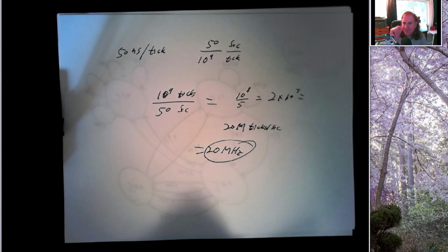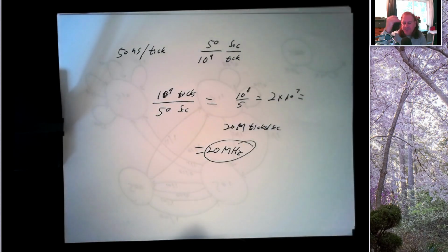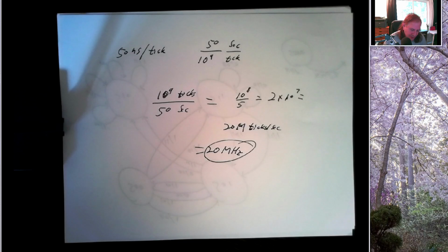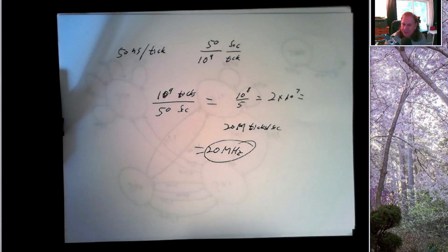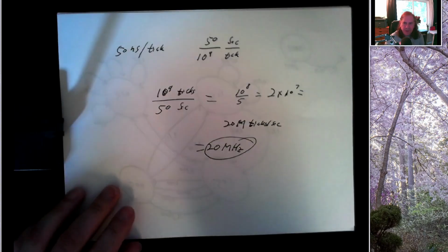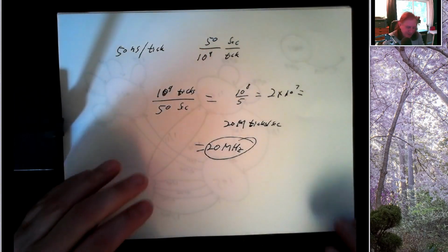And it's just a matter of using very, very small devices with very low voltages, so you don't have to swing a voltage all the way from 0 volts to 5 volts. We swing it maybe from 0 volts to, you know, 0.5 volts, and maybe that registers as a logic 1. And very low power, right? Not enough power to drive an LED, not enough power to raise the voltage on a big pin coming out of a chip, but just a little tiny bit of current, right? Small number of electrons, because we're going through a wire that is, you know, a few angstroms across perhaps. This is why integrated circuits run so much faster than circuits built out of discrete components.